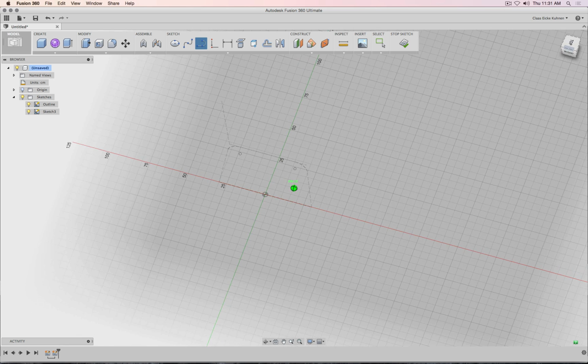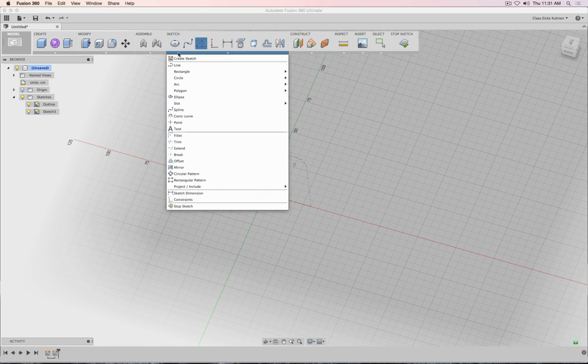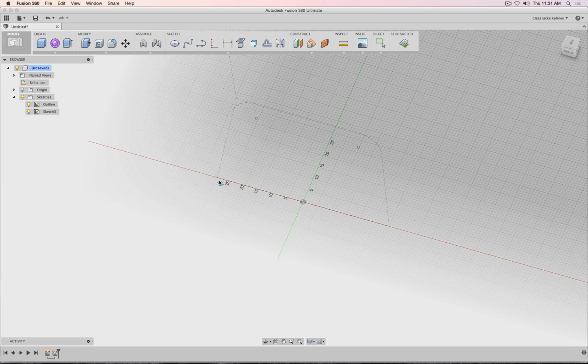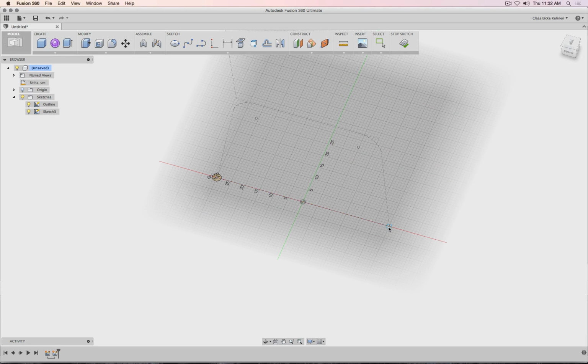And for example, I could start with the circle diameter, go to the back, and say maybe, what should we say? Let's say 3 centimeter pipe. You can change this later anyway nicely. And let's do the same in the front, 3 centimeters. Okay. Maybe those constraints we want to pull out a little bit more. Okay. So there's basically now the back and the front of our pipes.